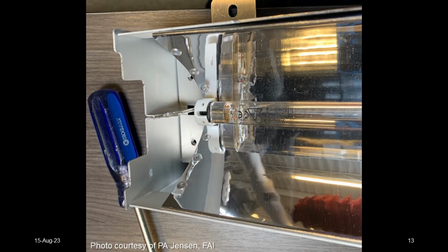So here we've opened up the fixture, and what are we doing? Well, we're just making sure everything is there and secure. And then we also take a look, is everything clean? Here's the reflector, and this was as received from the company. It has a bunch of dust particles, perhaps from the cardboard shipping container. It's very difficult to say exactly what it's from. So quite often, part of the initial evaluation of the fixture, one would also do an initial cleaning of the fixture. And we talk about that process in a bit.